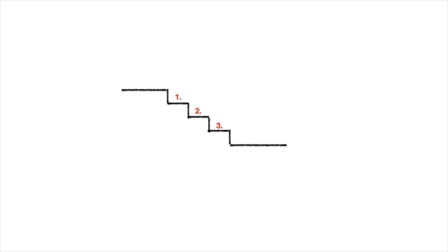So with 4 steps there are 3 treads, and using 2.5 times the riser for the treads, they're going to be 400 to 450 depending on material, so 3 times 400mm is 1.2 meters. Now your material and manufacturer specification will dictate the fall that you need to use.